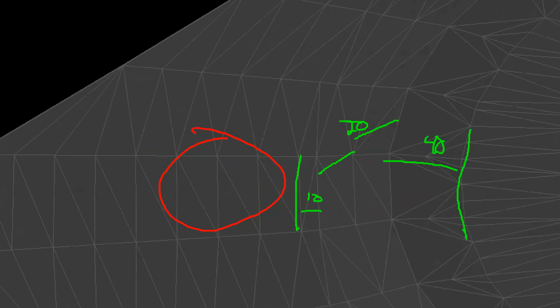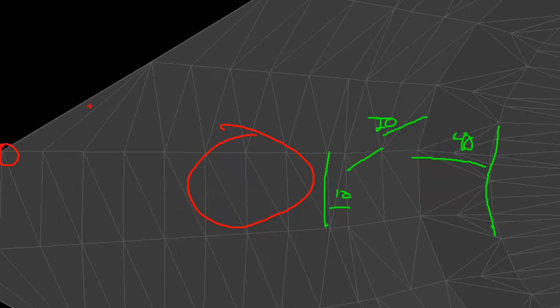So this is my right of way. I'm going up for 40 feet, going down for 20 feet twice. I've got my backyard building pad that's 10 feet. And then from here, the rest of this is all floating because again, I'm taking my elevation from my existing surface and that feature line hierarchy out there in the back.